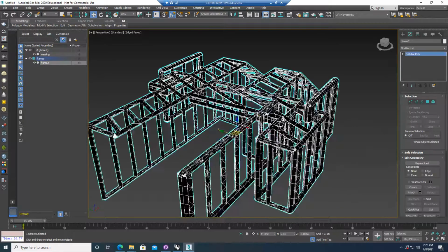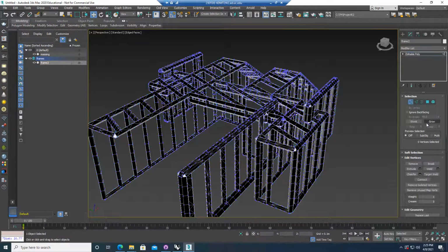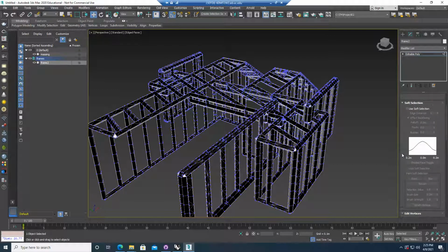This one is transferred directly from Rhino. Of course, I can do the same thing like a quadrify, I can turbo smooth. I want to show you some other ways you can manipulate. One way is soft selection. This is actually pretty handy. If you choose soft selection and pick a point, you basically pick a range of points. Here you can define the falloff, maybe let's do 2 meters, really large. Right? So here you can see the range of points.